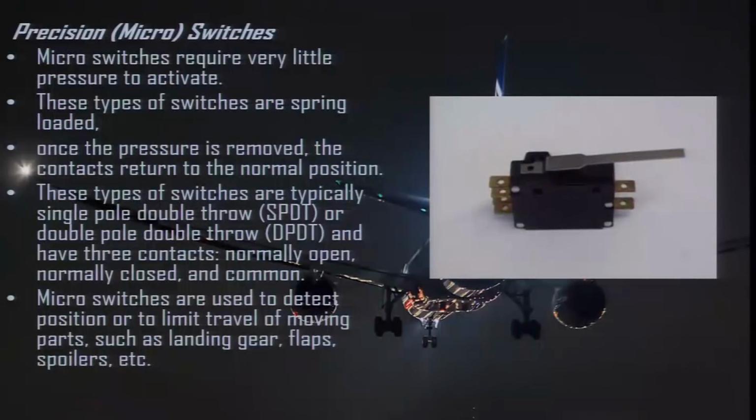Precision micro switches. Micro switches require very little pressure to activate. These types of switches are spring loaded. Once the pressure is removed, the contacts return to the normal position. These types of switches are mainly single pole, double throw or double pole, double throw and have 3 contacts: normally open, normally closed and common. Micro switches are used to detect position or to limit travel of moving parts such as landing gears, flaps, spoilers, etc.